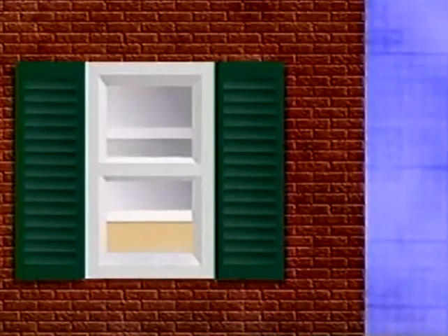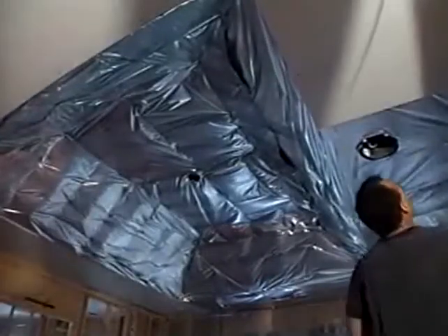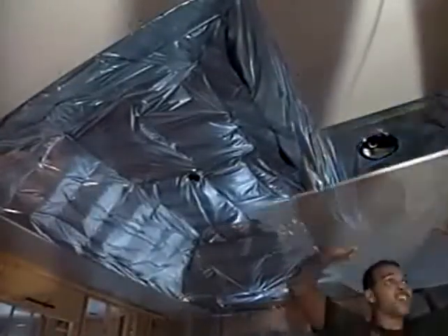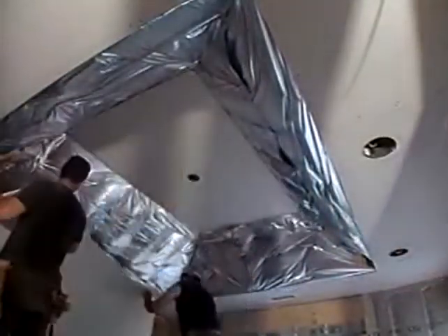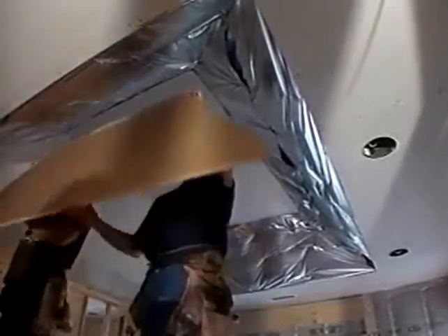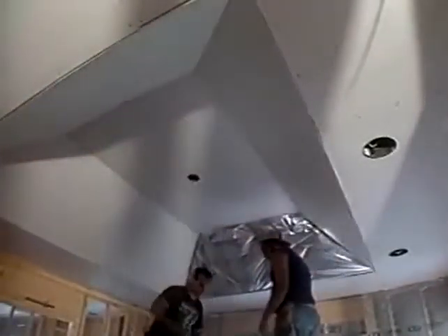In typical residential construction, the average home has air leaks equal to a window opening of about a foot. With proper air sealing, we can get that window nearly closed. We do that by sealing up unwanted holes in the air barrier. The air barrier of a home is the boundary which separates the indoor conditioned air from outdoor unconditioned air. A good example of this is the sheetrock ceiling between the living space and the attic.